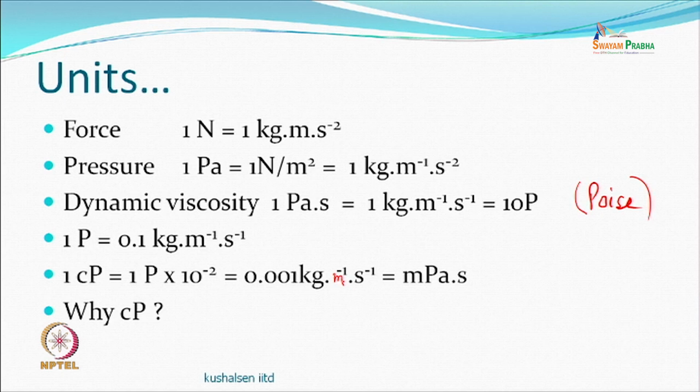Generally, if you see the viscosity of a paste, of water, or of another liquid, people talk in centipoise. Otherwise, theoretically you can talk about dynamic viscosity in Pascal second, or in terms of poise. So why talk about centipoise? Interestingly, at 20 degrees, the standard temperature and pressure, the viscosity of real, distilled water is approximately 1 centipoise.